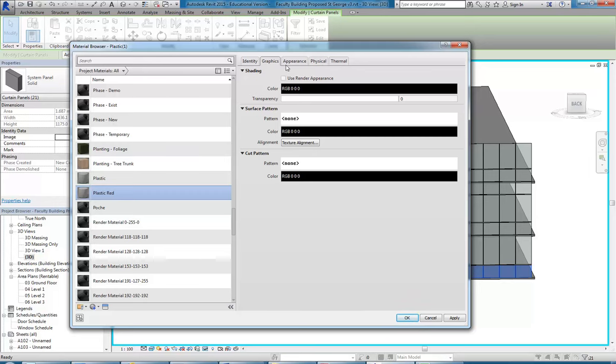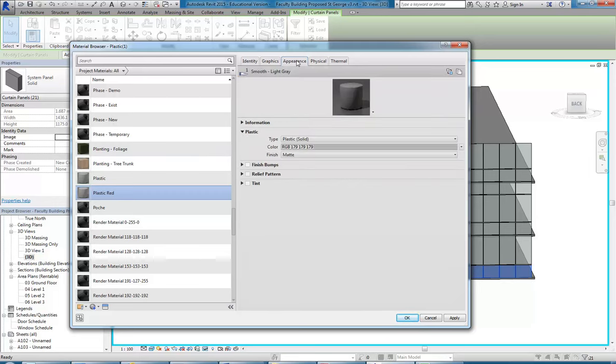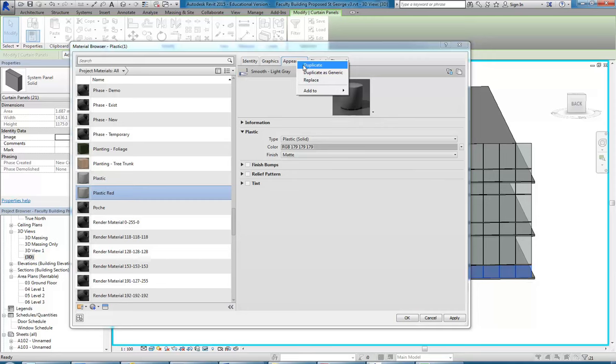Would you have to create a new material? You don't have to, no. What you need to do is go to appearance and duplicate that as well. Yeah, it's doing the two duplicates that everyone forgets. And look, it's actually I think one of the worst decisions they made when the developers were bringing in the new material system for Revit in 2012 or whenever it was. But it's just the way it is.